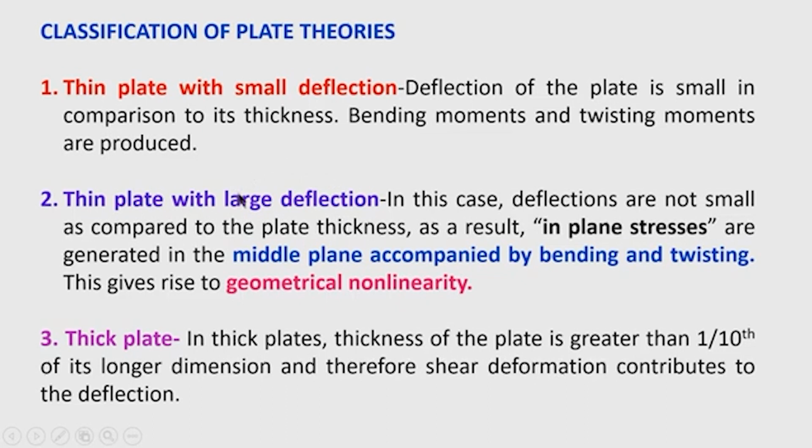So, therefore, due to large deflection, the geometric nonlinearity will be produced, and as a result of large deflection, in-plane stresses are also produced in the plate in addition to bending moment and twisting moment. So, the in-plane stresses that are produced will alter the nature of the problem, and the governing differential equations of equilibrium and solution techniques also will be different compared to the thin plate with small deflection.